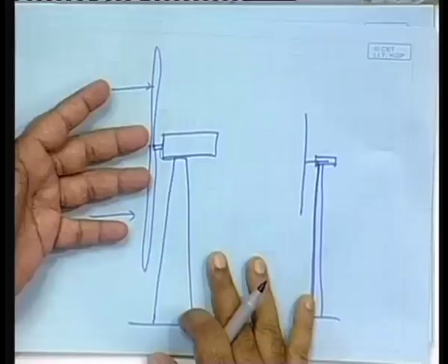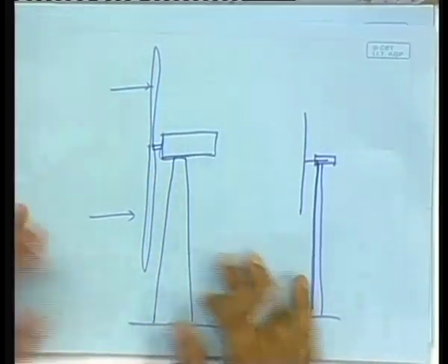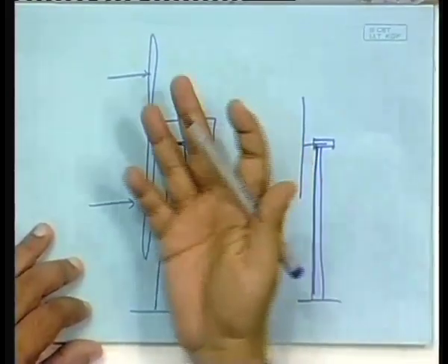You have already seen that there are constructions, vertical axis wind turbine constructions, which do not need a tower. There the whole cost in the tower is less, and therefore, they are far easier and far cheaper to construct, but they have the problem that if you have the tower that reaches higher altitudes, at higher altitudes you have got higher wind speeds, while if something is constructed close to the ground, it does not have access to the high wind speeds. But that is one advantage of having a tower. That is also the disadvantage, that there is a large expenditure in the tower itself.